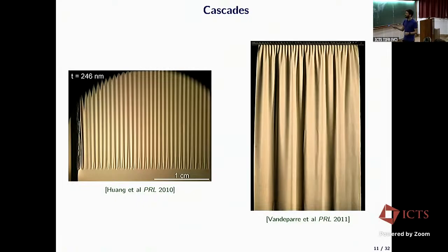So the edge is here, and you see that the capillary forces at the edge want to make the edge flat, so there is another energy term at the edge that penalizes departure from a flat state. And so the wrinkle wavelength is much smaller at the edge, and then you go to the infinite wavelength here, okay? You have this change in wavelength.